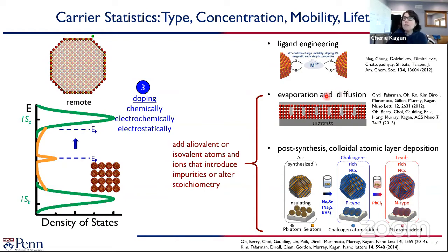And then not only can you use evaporation of metals, which is a physical vapor deposition process, where you use an evaporator, but also you can use approaches consistent with handling things using solution-based methods. We looked at what we consider a post-synthesis colloidal atomic layer deposition process. It has its analogy in approaches that people developed, whether they call it SILAR or colloidal atomic layer deposition, while the particles were still in the synthesis pot.